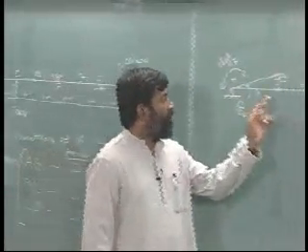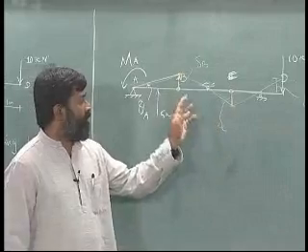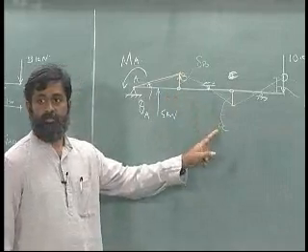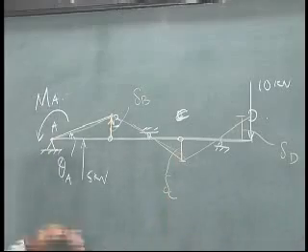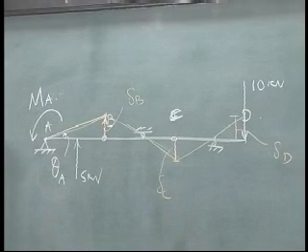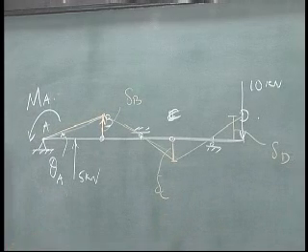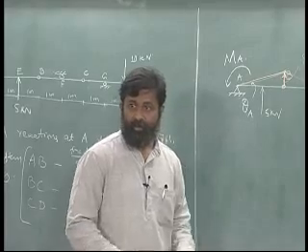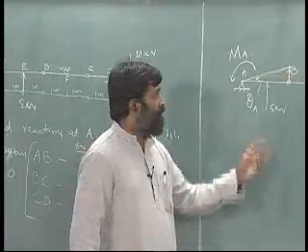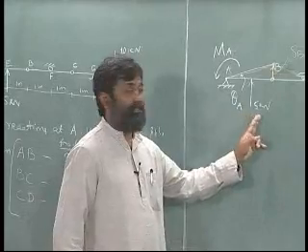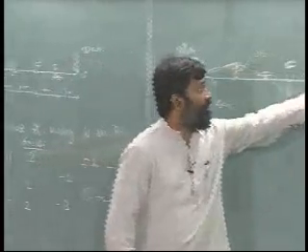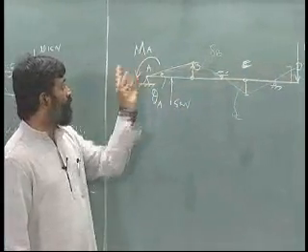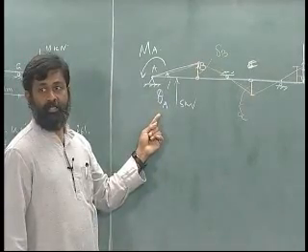Now, once I find out delta B, from that I will find out delta C, from that I will find out delta D. So, what I am going to do now is find out kinematically admissible virtual displacements, because now we know we have to do that in order to provide the virtual displacements at 5 kilonewton and 10 kilonewton, apart from the virtual rotation that is already given.